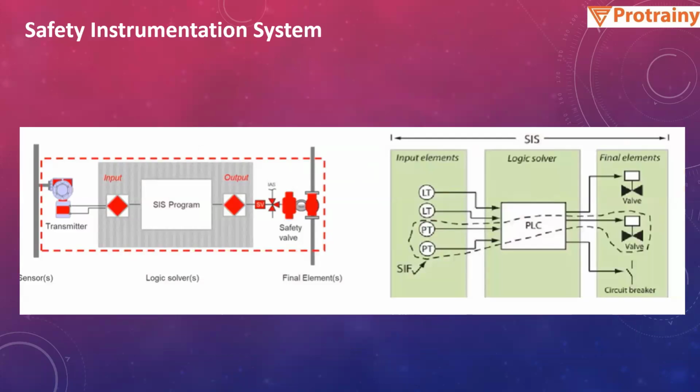So this is also another instrument system, which is safety instrument system. So it is also based on various inputs, like this is level transmitter, pressure transmitter. It will give input to the logic solver or PLC, and then based on the PLC it will be providing data to the actuator. So you can see these are the motor operated valves.